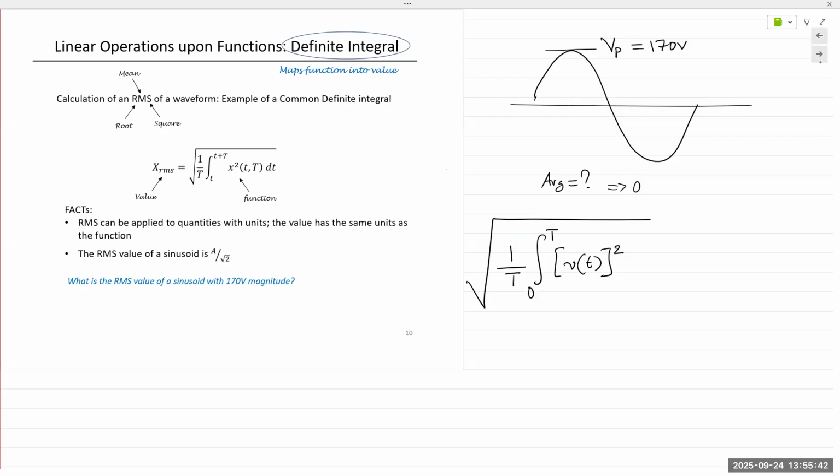If we take an oscilloscope, most oscilloscopes would be able to measure that kind of voltage. You are not going to do this in the lab. I'm just letting you know that it is possible. You could take an oscilloscope, take a 1:10 ratio probe, and stick it into a power outlet, and we can observe the waveform. Okay, we are not going to do that.